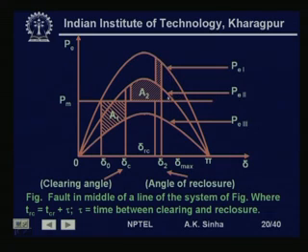Now, in this situation, if the fault was a transient fault, then the decelerating area available will be much larger. It will be like this area which will be available, because now the operating point will be on this characteristics. But in case the fault was a persistent fault, then from this point the operating point will suddenly drop to this point, rather than going up, and we will have more acceleration available, and the system may become unstable also in such situations.